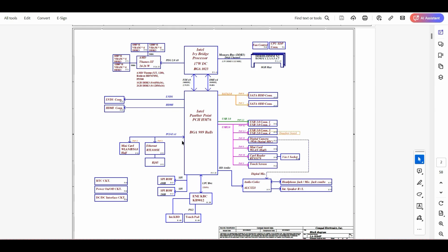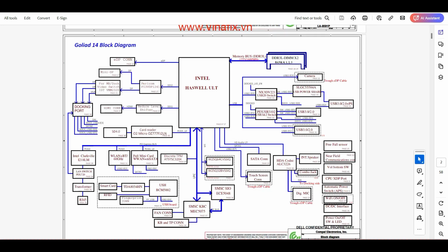In Inspiron there are very few components. See, compared to all laptops, the USB and SATA, HDD, ODD, camera, card reader, everything will be common. But in the Latitude series, many, many components are there. So here 2 IO is the major specialty in the Latitude series. Here you can see the SIM card option also, and the main TPM section, okay, and dock. See, dock is the major thing. These are the components this particular motherboard has to handle.